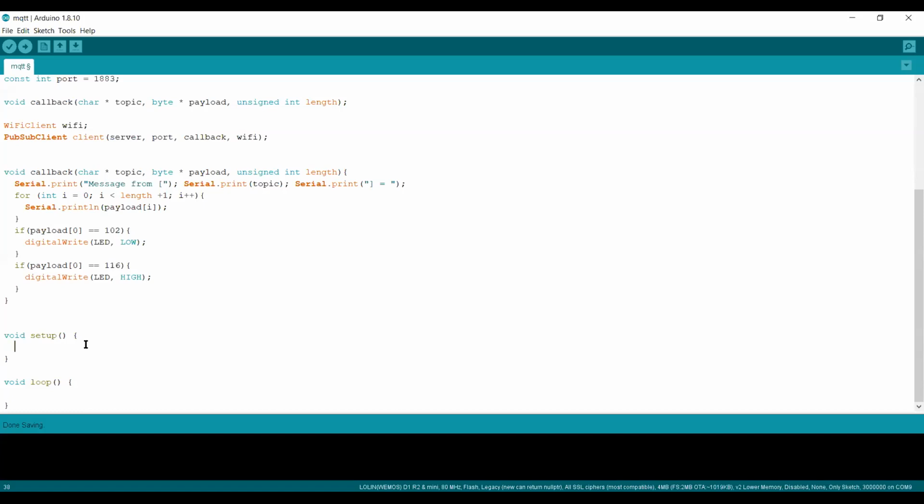define some parameters. First of all, we will define our serial connection using the begin method. And then we can use Wi-Fi.begin and pass in the SSID and the password. And again, if you are familiar with Wi-Fi connectivity, or maybe you attended the last sessions, then we need to check for the connection of our Wi-Fi before we move on into the code.